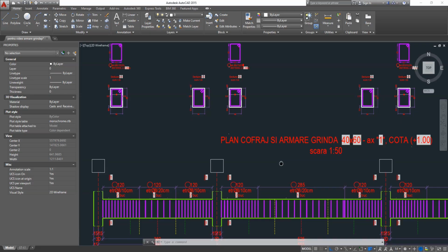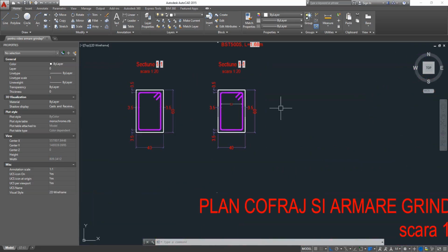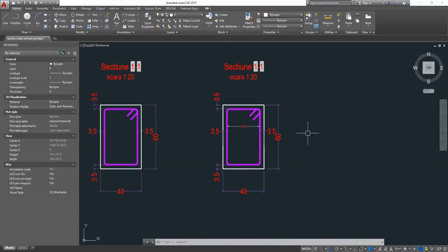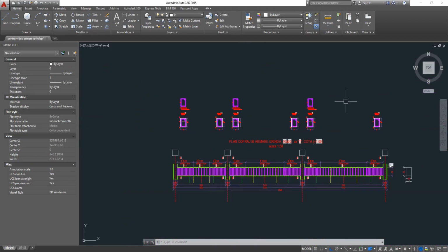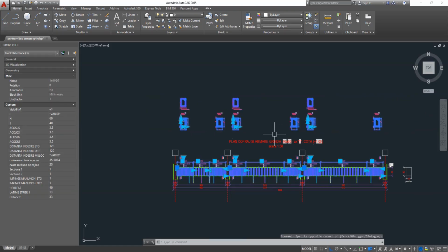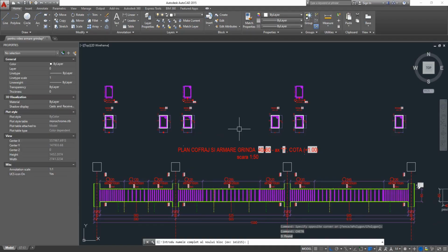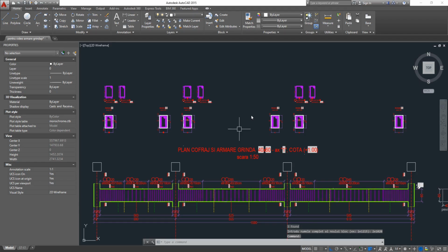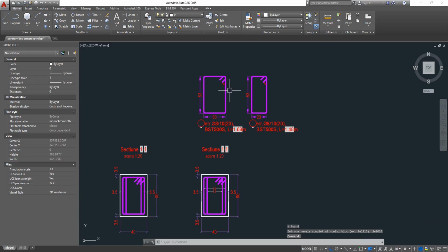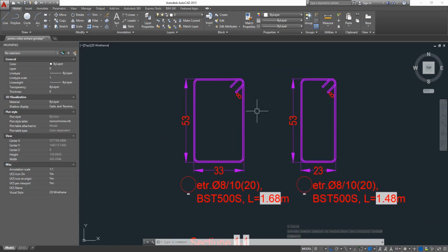So for this exercise, we want to use, in fact, a rebar cage of 2 stirrups per section. So we're going to select the stirrups again, and we change the package of stirrups. Let's say 2 stirrups at a pace of 10 and 20 centimeters. Okay, it takes a little bit longer for the Lisp to compute, and now we have two stirrups instead of one per package.